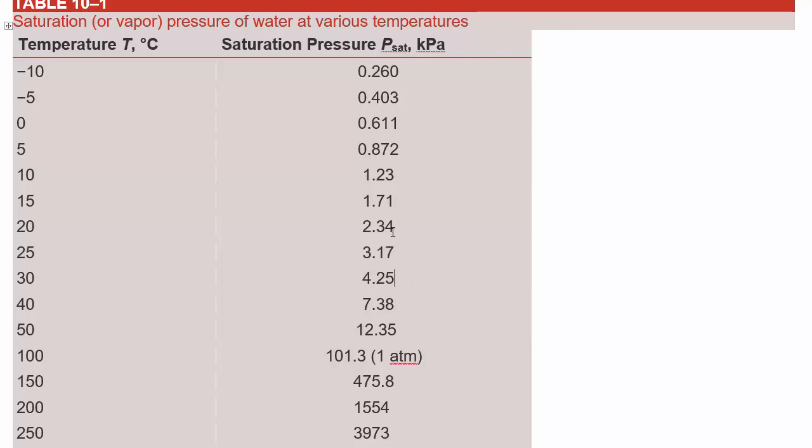So that means it's somewhere in here. So 30 degrees, 60% humidity means, if we've done our math correctly, then the dew point should be maybe around 22 degrees or 21.5.